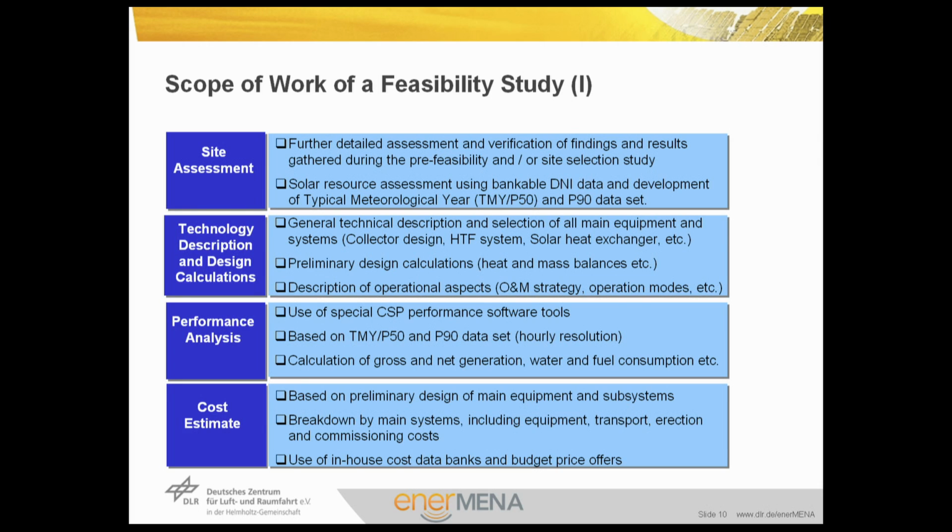It is important that we calculate the gross and the net generation. The island mode operation principle should be known. You have to know also the own consumption by giving a list of the main consumers to better understand to which extent the plant will be available in case of failure in the overall network.